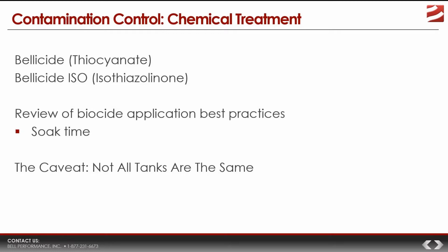Biocides need time to work. The period of time that you allow them to work, I've called it residency time, but the technical term would be soak time. So you ask a fuel microbiologist, how long should my soak time be? And the microbiologist would say, well, optimally speaking, 24 to 48 hours. If you've got a smaller tank, 12 hours could be optimal. But not all systems are the same.